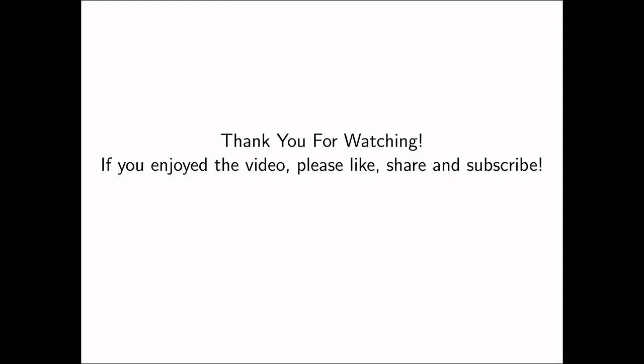That concludes this episode. In this episode, we introduced the op-amp non-ideality of finite bandwidth and explored its implications on the closed-loop gain and bandwidth with different feedback loops using an example op-amp in LTspice. In the next video, we will continue with the op-amp non-ideality of finite bandwidth by going over stability in op-amp feedback, and how to determine if an op-amp circuit is stable, as well as discussing the concepts of phase margin and gain margin.